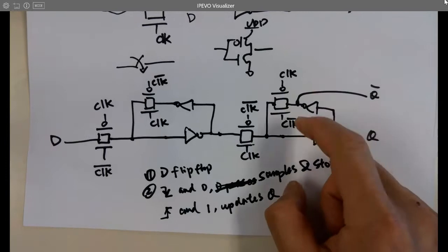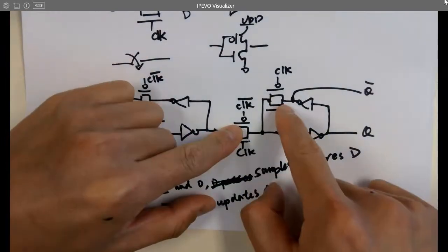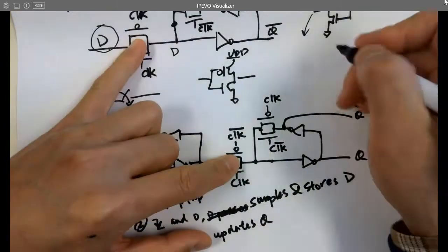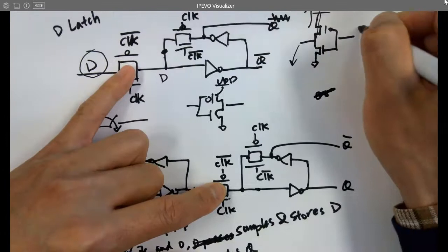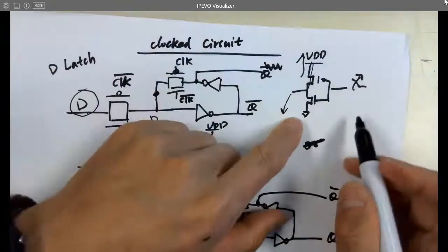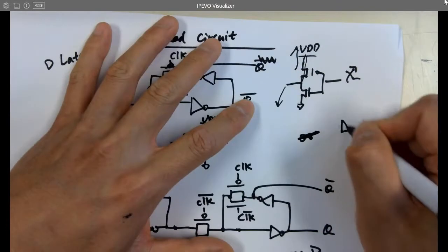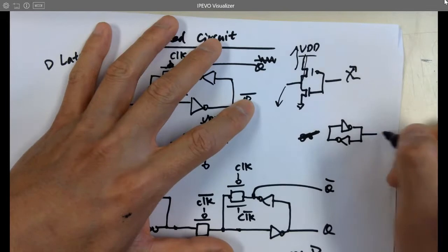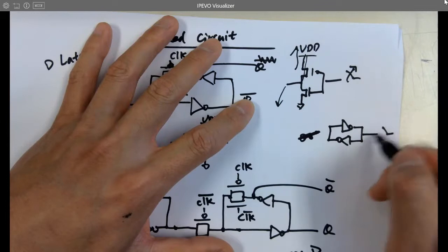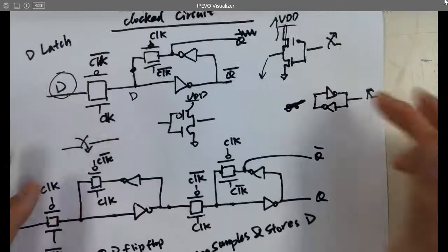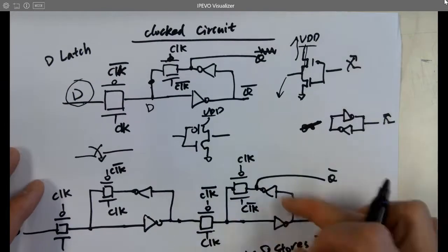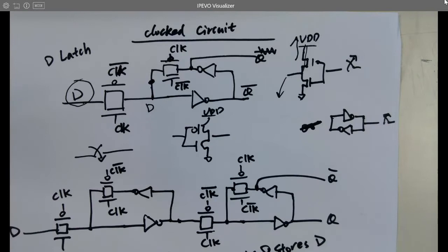This is a latch, right? The latch holds value. Okay. So whenever this is off, this is on, right? Remember what I said last time on Monday when we were talking about the inverter? If you open the switch, the inverter is not able to store anything. But if you have a latch, previously it's feeding a signal to it, but after you open the switch, it still has either 0 or 1 on one side, right? The latch stores it, but the inverter couldn't store anything. That's why we are using a latch here. Yeah, this is holding a value or storing the value. Yeah, only 1 and 0, right? Yeah, good point.